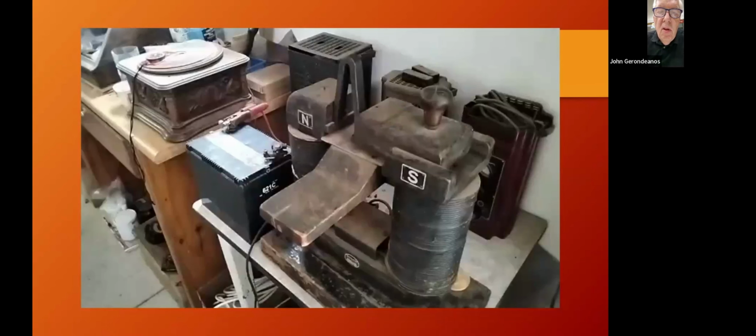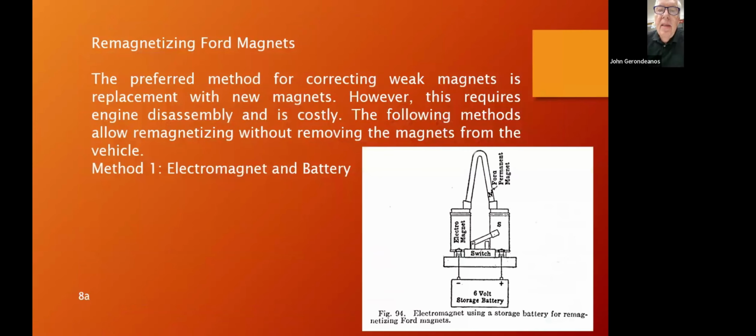Oh, it's not really mine, but I have it on permanent loan in my garage. And the battery, and you hit that battery with your battery terminal, or you throw the switch several times, and you'll see a fairly large arc. Now that arc or spark is due to the inductance of the magnetizer, and something called Lenz's law: the current wants to carry on flowing in the inductance after you remove the voltage.